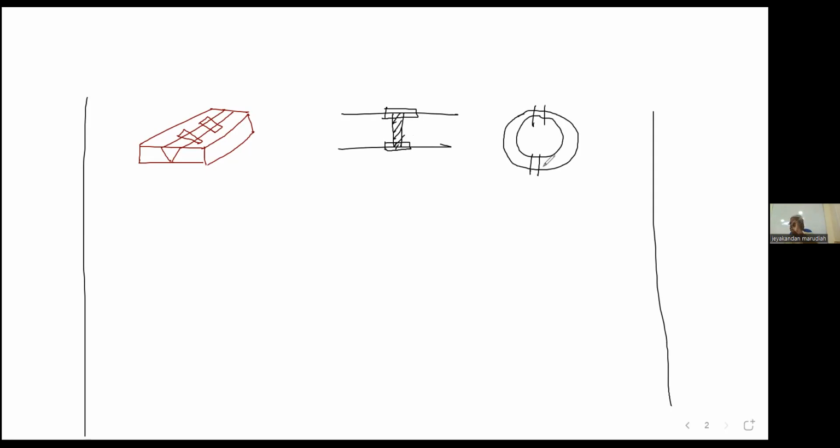Now, tensile specimens: after cutting, you can prepare 3 types of specimens. Reduced tensile specimens, turned specimens, where turned means round shape, and full diameter specimens. Full diameter means if the pipe diameter is less than 3 inch, we can use the full pipe. For our exam, the question will generally be based on the reduced tensile specimen. So what is meant by reduced tensile specimen? Suppose this is your specimen. We will reduce it at the center, like this.